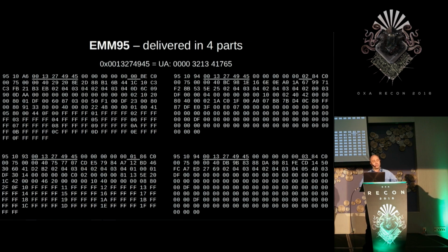EMMs are split into 4 parts. Each part contains a portion of the subscription information for the set-top box. A category key is calculated from each of the 4 parts, and the key calculated for each part must match, or these EMMs will be rejected and all the authorization data and category key will be wiped out.